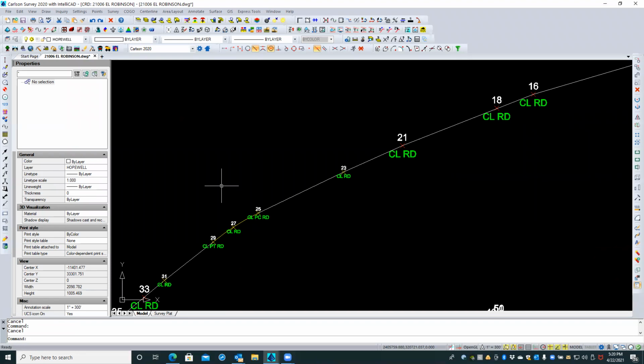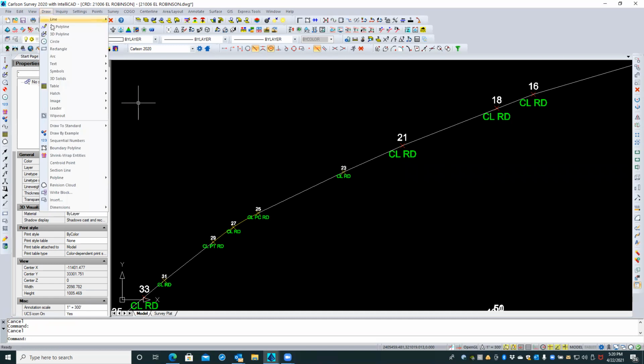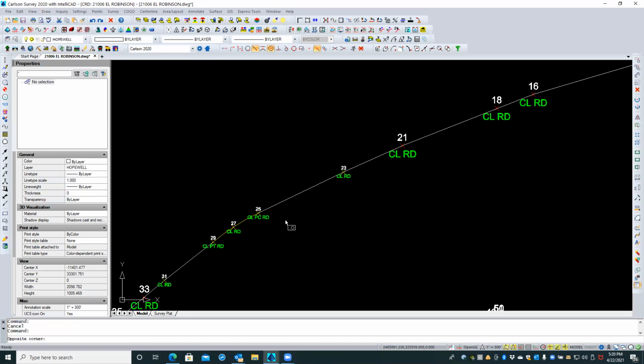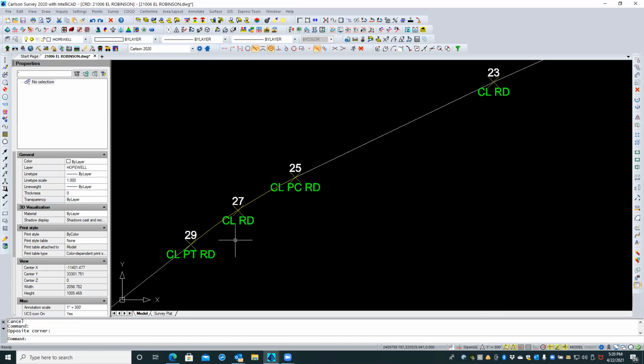Should have been an easier way, Mike. I mean, there could be. You could do these given the tangents, but you'd have to know one of these values, and you could choose. You could even say the tangent length. I might just want to measure from here to here. I'll see what that happens to be, and that's 104.2. So I might call it a 100-foot tangent, and then I might go.